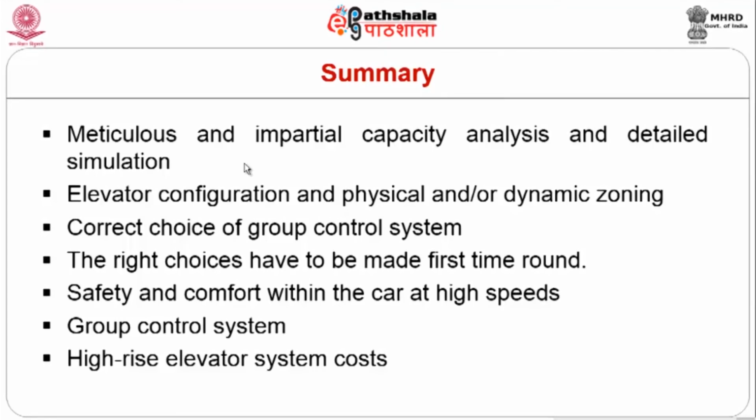Therefore, meticulous preparation and planning are needed before getting into detailed simulation. Elevator configuration and physical and/or dynamic zoning is very important in terms of planning. Correct choice of group control system is also vital. The right choices have to be made the first time round.